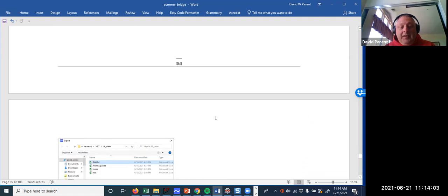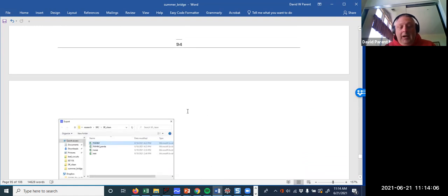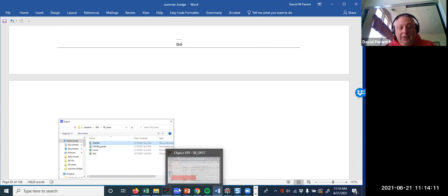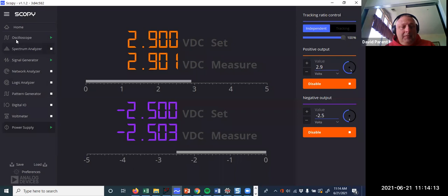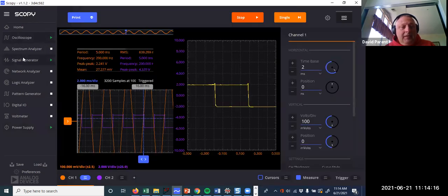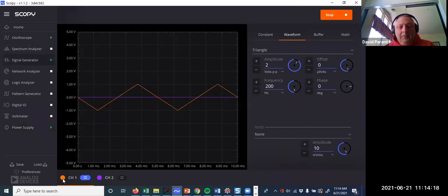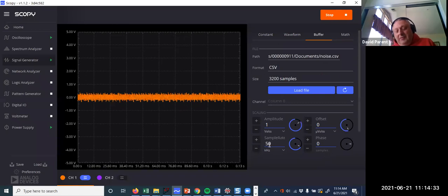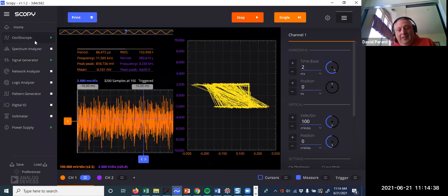I just want to orient you to things that aren't in that video, or just reinforce them. An important thing is when you come to do the noise source, whenever you come back to it, it changes the sample rate to 10 megahertz. So you've always got to bring that back to 50 kilohertz. Otherwise, it's not going to work.